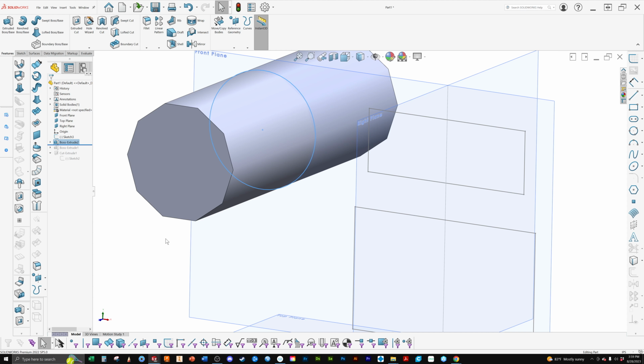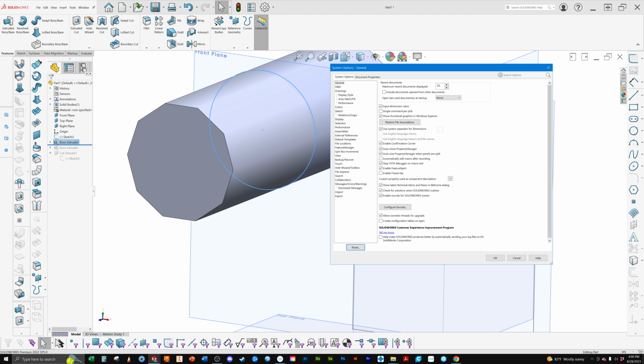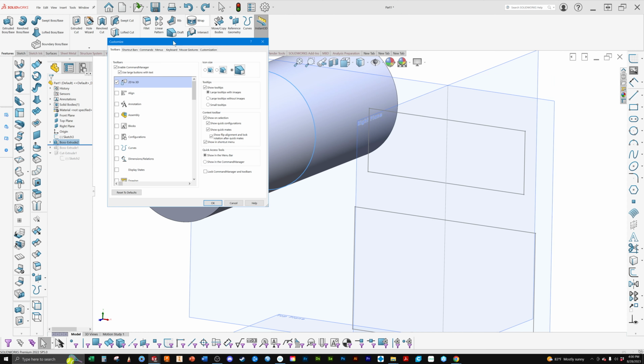So for people with slower computers, turning that down will help your screen and will help your resolution and your video card keep up. For those of you with faster computers that want to make sure, well, is that circle a circle? You can come in and the image quality, by turning that up, you see that it visually displays the way it's supposed to be. Even I have to turn that down sometimes if I have really, really large assemblies, just to help my computer move a little bit faster. We don't need to worry about that.